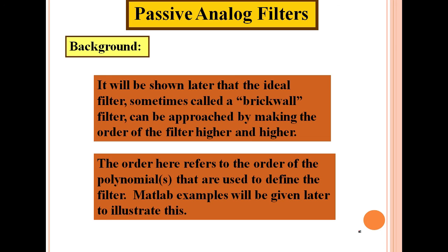Then the analog filter is categorized basically into 4 types: low pass filter, high pass filter, band pass filter, and band stop filter. Going further, there are also the notch filter and the all pass filter. This is an advancement, with slight modifications in the circuitry to design the all pass filter and notch filter, and there are some applications of the notch filter and all pass filter also. Then we have seen the ideal characteristics and the practical characteristics of all 4 types of filters.